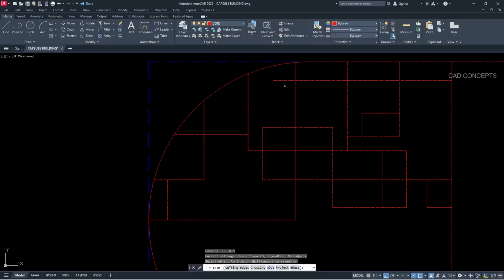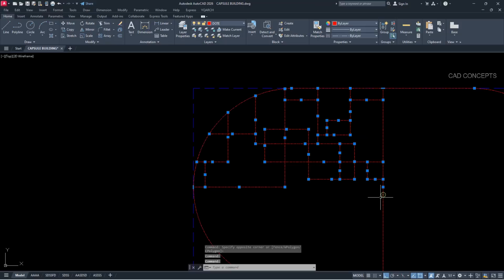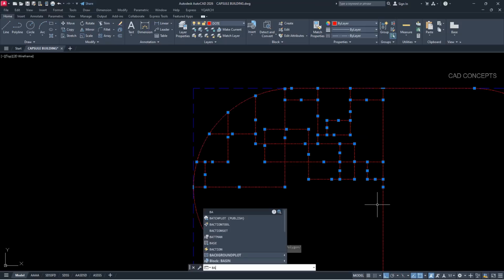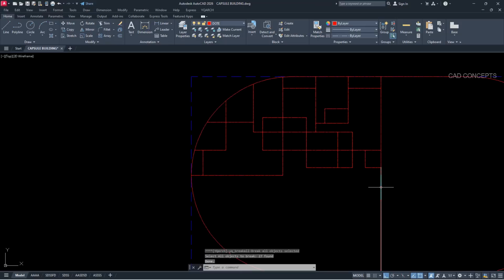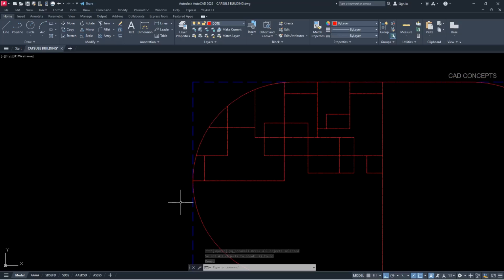So let this extend up to here, and we'll keep one balcony here also. Okay, let this part stretch up to here. Select all the lines, type BA. We will explore these lines to place our walls everywhere. So wherever we join flat to flat or outside, we'll keep 20 centimeter wall, and inner we'll keep 10 centimeter. So just select where we are keeping 20 centimeter.